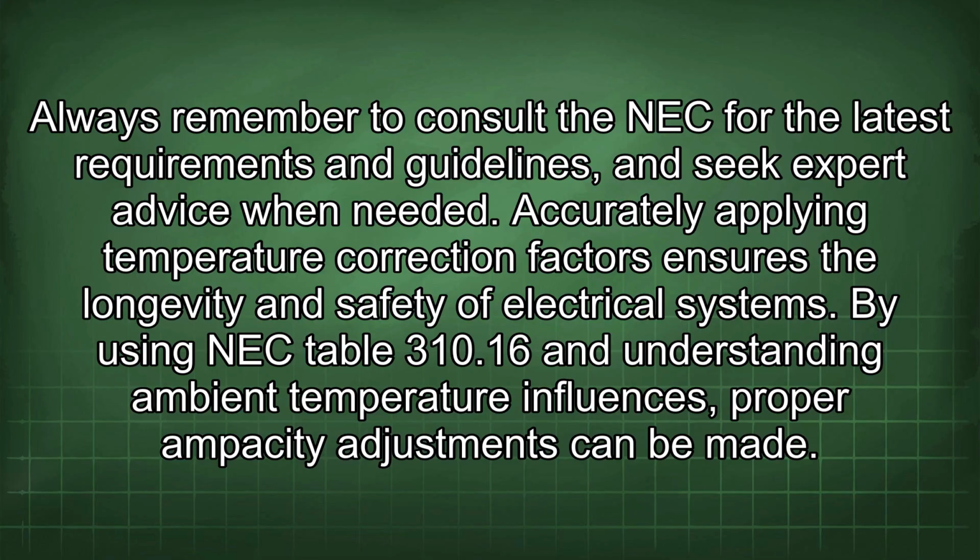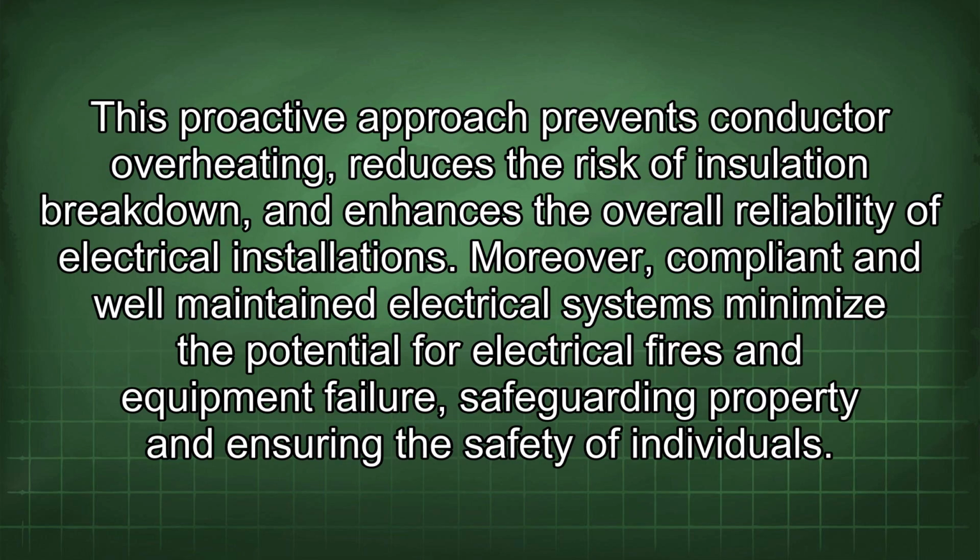Accurately applying temperature correction factors ensures the longevity and safety of our electrical systems. By using NEC Table 310.16 and understanding ambient temperature influences, proper ampacity adjustments can be made. This proactive approach prevents conductor overheating, reduces the risk of insulation breakdown, and enhances the overall reliability of electrical installations.